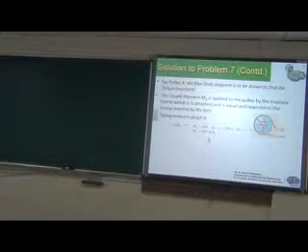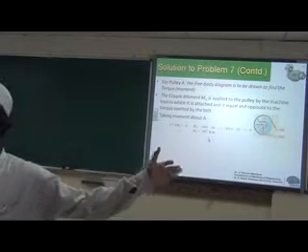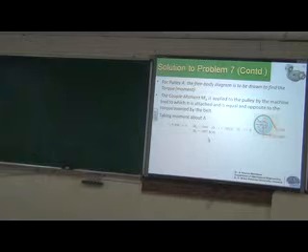T and its perpendicular distance is the radius. The tension exists on the belt, and the belt is placed tangentially with the wheel, the pulley. So T into its perpendicular distance is the radius only. That is why we have taken T1 into A plus T2 into A. Considering the direction, it becomes minus. Anti-clockwise positive.